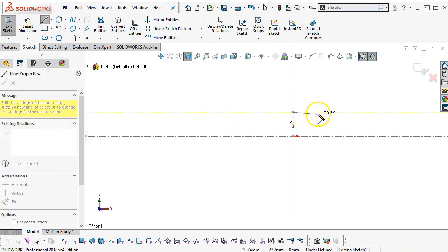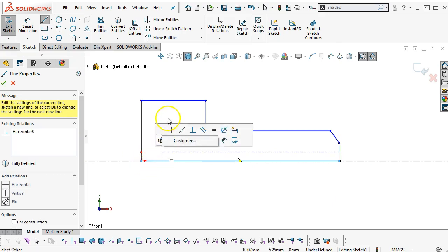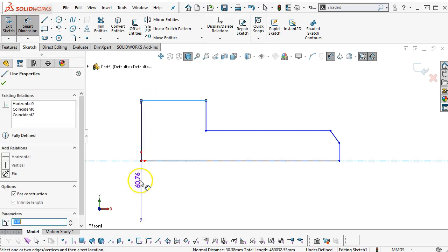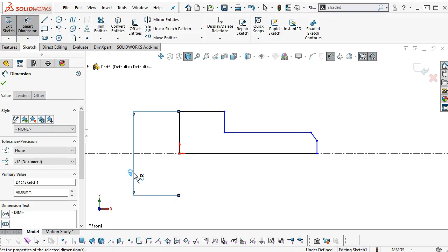So an up and over, down, and then the question is, do I include the chamfer or leave the chamfer as a separate feature? We'll go ahead and include it. Oh, and then I do want to close this off, otherwise it's going to ask me to. So dimension. Overall, we have a diameter of 40 millimeters, and the outside, .28.